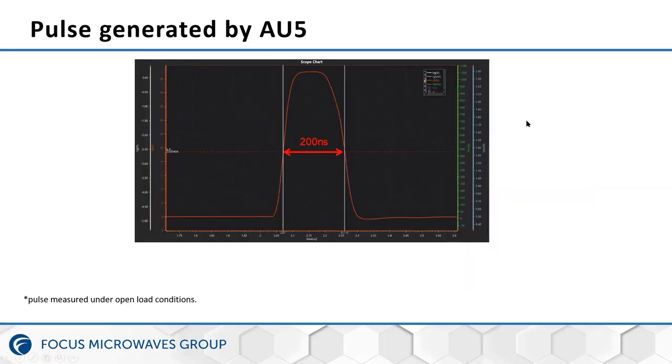Now, as the pulse width becomes narrow, here represented at 200 nanosecond pulse width, we end up with a rounded kind of shape. The reason for this is that the rise and fall time of the pulsar head is around 50 nanoseconds, which means that we have a very small measurement window within the pulse. So if this pulse is not clean and we have some ripples and overshoots here, the measurement within this pulse will not be stable.